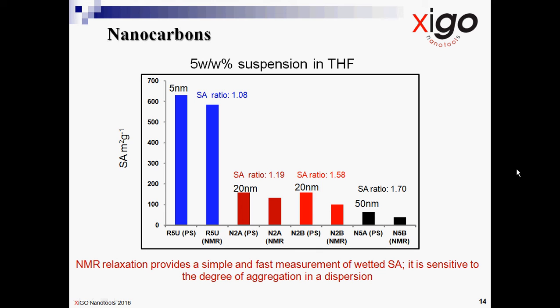The application performance of a carbon black is determined by its nature, including how it was manufactured and the level of dispersion achieved in formulation. The most important physical properties include particle size and wetted surface area. The particle size exerts the greatest influence on color. The finer the size, the darker the color. All carbon blacks contain aggregates and agglomerates that impact the total wetted surface area. Because high surface area is also associated with greater blackness, aggregation needs to be kept to a minimum, and any analytical technique that can provide an indication of the degree of aggregation is most welcome.